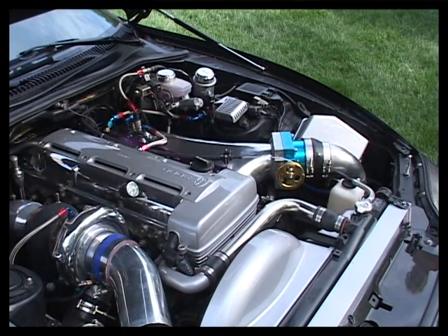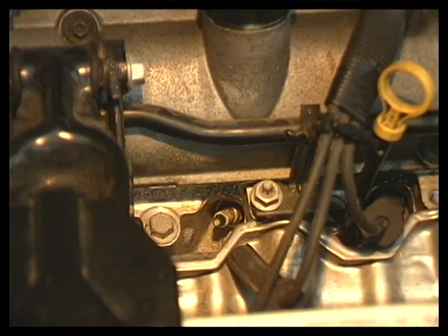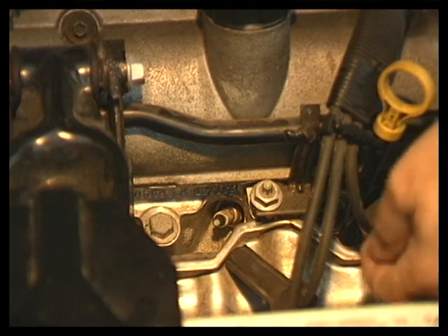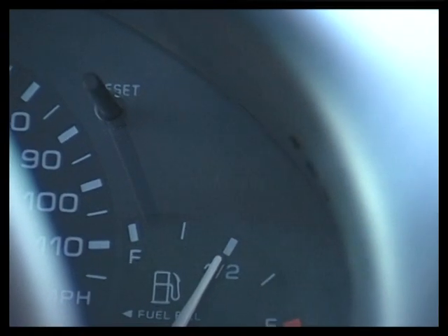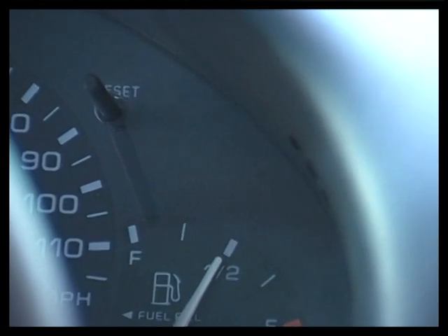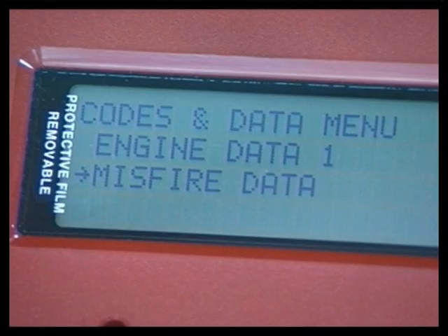One example with OBD2: engine misfire, that is, the engine not igniting and burning fuel mixture properly, will make a malfunction indicator light in the dash blink on and off. This is to warn that the misfire could overheat and damage the catalytic converter. This alerts the driver that the vehicle is being damaged and should not be driven.